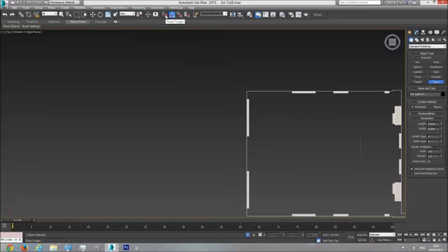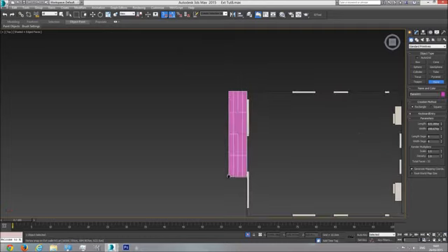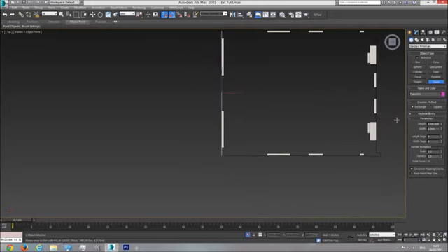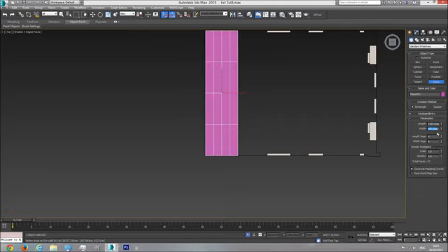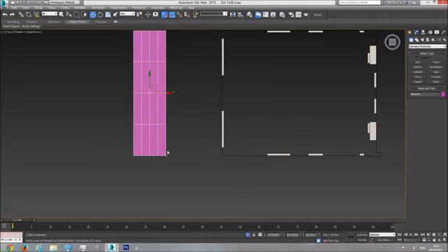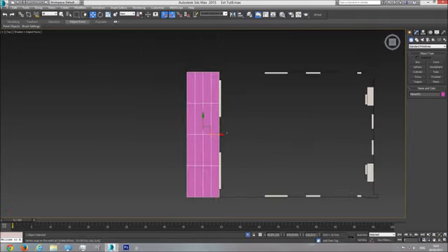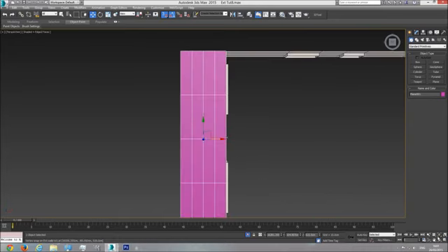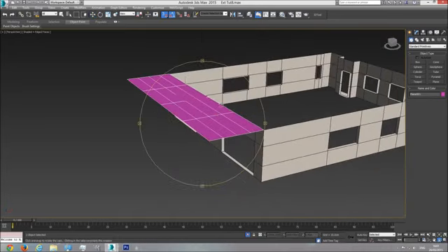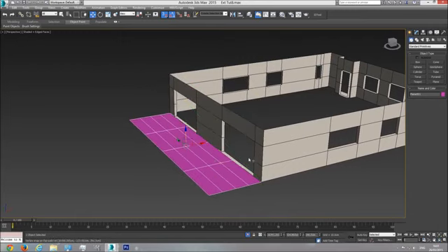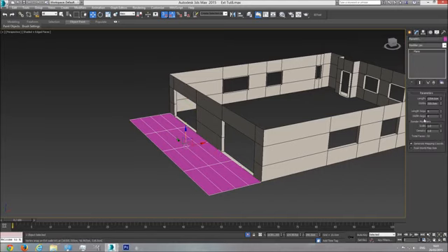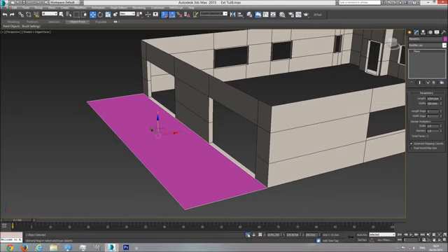I'm going to snap toggle on and just create a box here from here to here and make the width 350 like so. Just take it out on the x-axis, I'm sorry, this direction, and from this point just put it aligned with the walls here. I'm going to take this floor down on the z-axis to the beginning, to the opening. I'm going to make the width segments 1 and the length segments 1. And now let's unisolate everything.